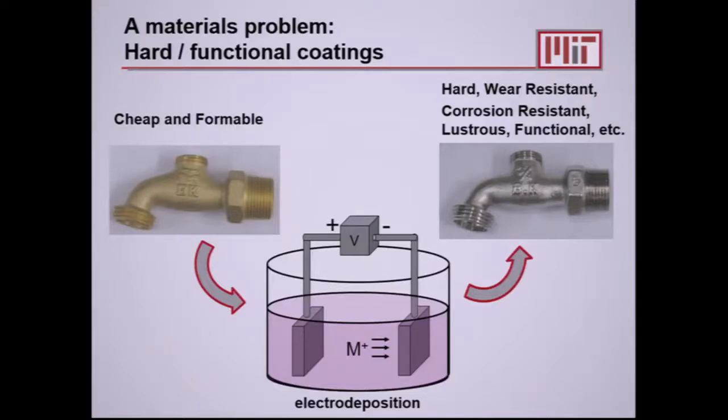And so I chose early on in my career to focus on electrodeposition as a means of rendering high value metal. Electrodeposition, you all know it, you probably all did it in high school, right? It's an aqueous solution with dissolved metal ions from salt. You render your component the cathode in the electrochemical reaction and flow some current through there, and you can put down nearly conformal coatings over very complicated shapes, and you can add really a lot of value to the component in doing that.